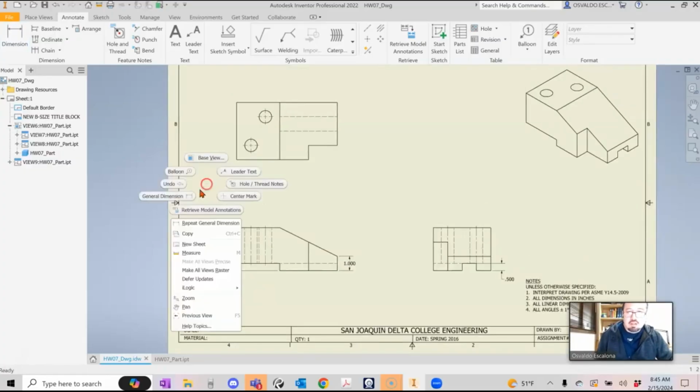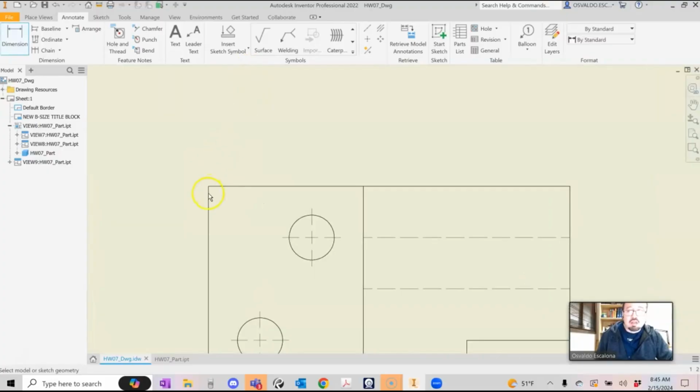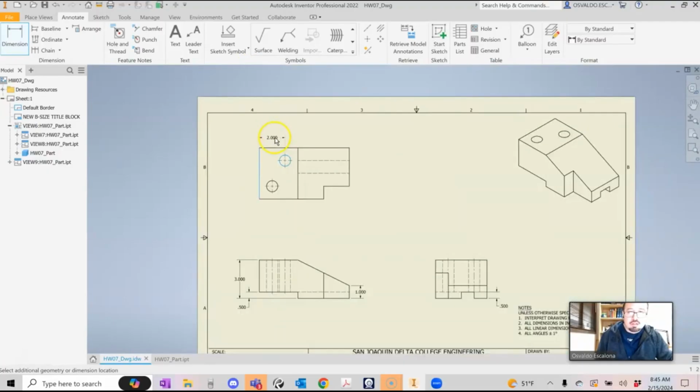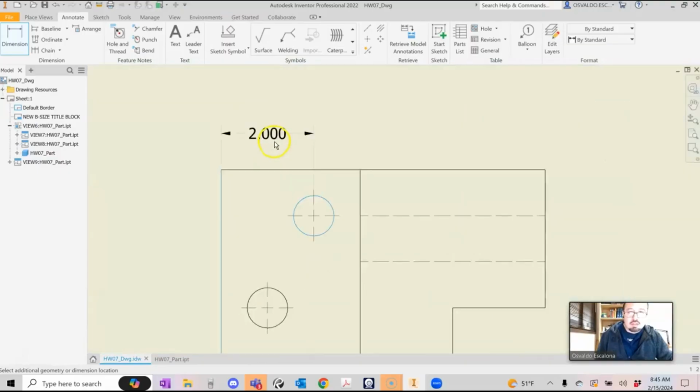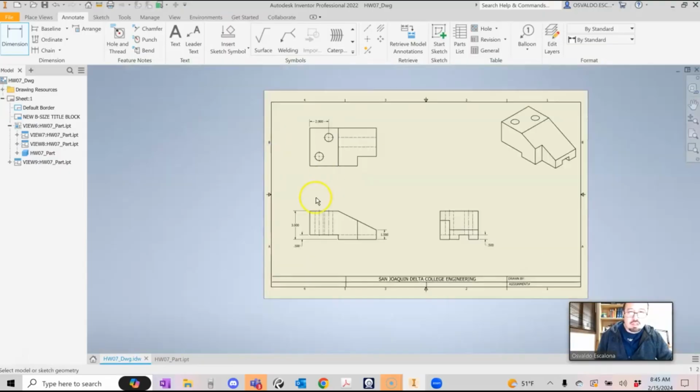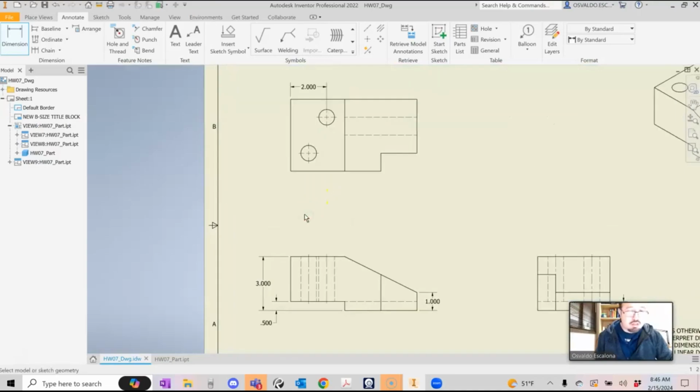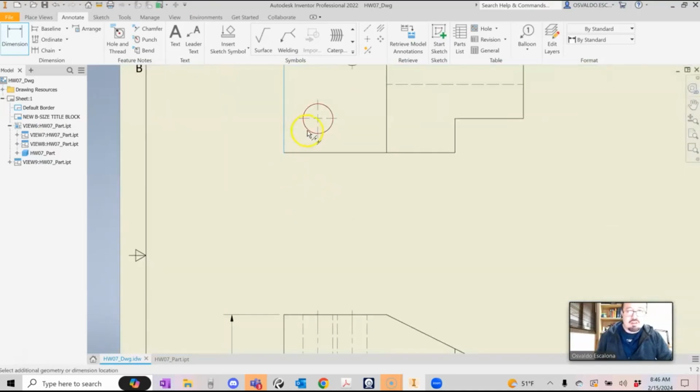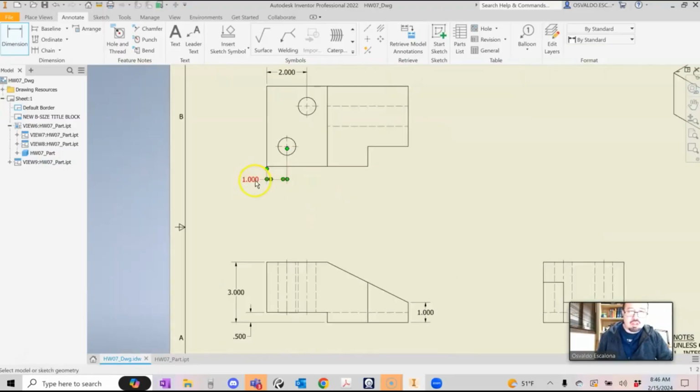The next thing, let's do the left. So I'm going to come over here and locate this hole from the left. Make sure I have about, it's a little too far there. It's about 3/8 of an inch. From here to there should be about the same, about 3/8. This guy is a horizontal dimension, so I don't need to have a shoulder. If you have something that is vertical and it's not on the inside, that's when you need a shoulder.